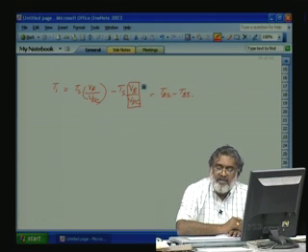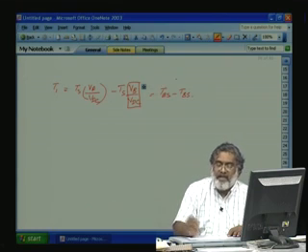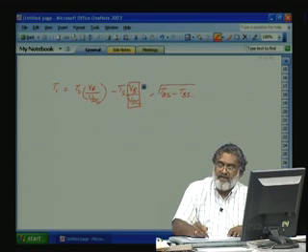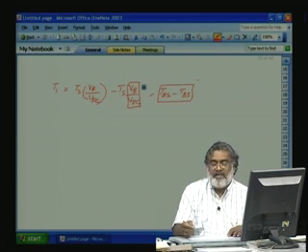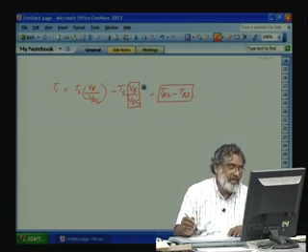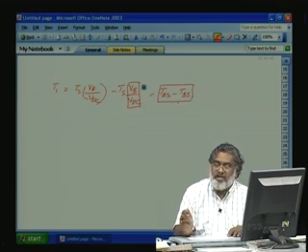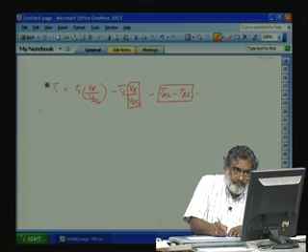So, what we are doing now is representing the sampled reference phase amplitude in terms of a time, in seconds, a fictitious time, that is proportional to Ts divided by Vdc. So, if VAS, VBS, the sampled reference phase amplitudes at that instant, are known, in sector 1 T1 is equal to that sampled value multiplied by Ts by Vdc for the A phase, minus Tbs, and it will give you T1. So, this is very easy. There is not much computation like sin alpha, root 3 by 2, all those things are not there here. It is very easy, you can find T1. Let us see what is T2 in sector 1.